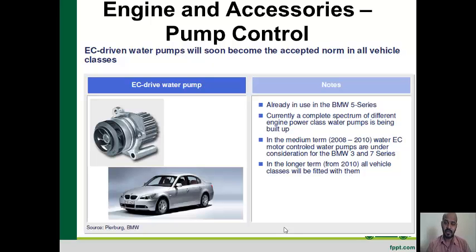Depending upon the engine output, the pump is operated. Sometimes the coolant flow need may be higher, and sometimes lower. But if it is coupled to the crank belt, it can't be controlled in real time. With an electronically controlled water pump, the pump is driven by a separate electric motor and controlled by the EMS. Based on that you can vary the pump coolant flow.